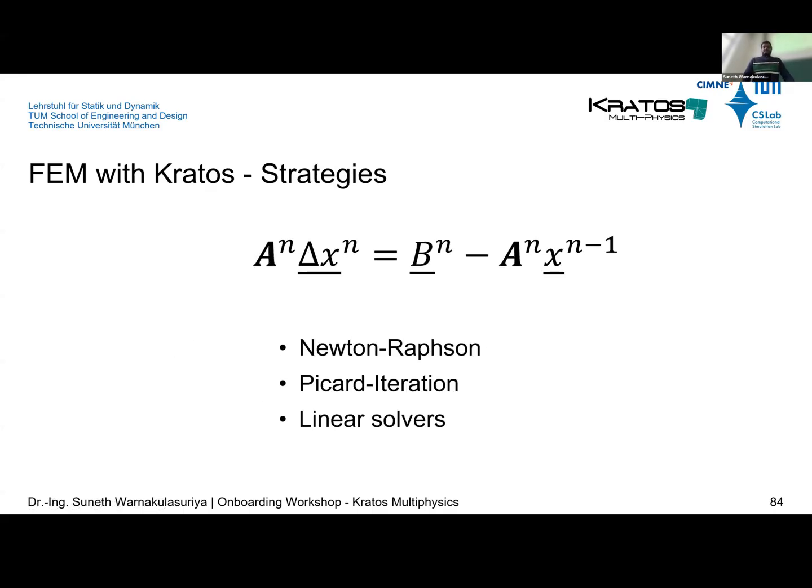After you get that, you now have the global system matrix, then you need somehow to solve it. That's also not an easy task, because those are not such nice matrices. Sometimes they are highly ill-conditioned. Sometimes you need special tricks. So whether you use Newton-Raphson, I think everyone knows when I say Newton-Raphson, but do you know Picard? Okay, you know fixed point iteration, right?